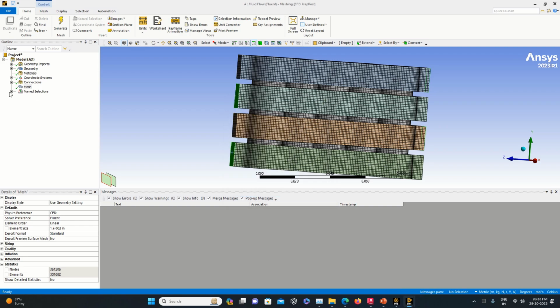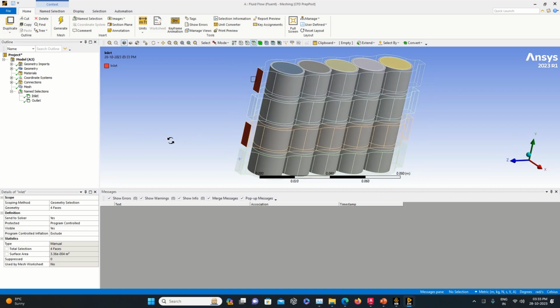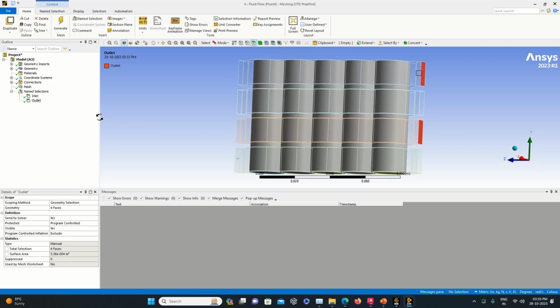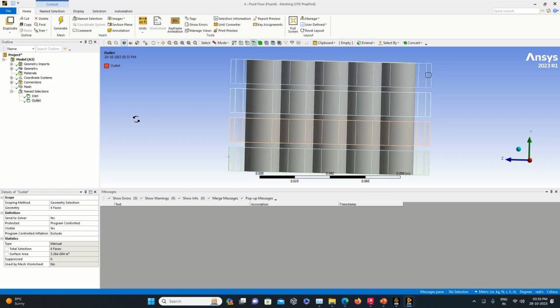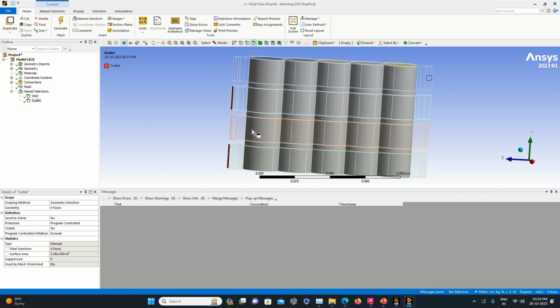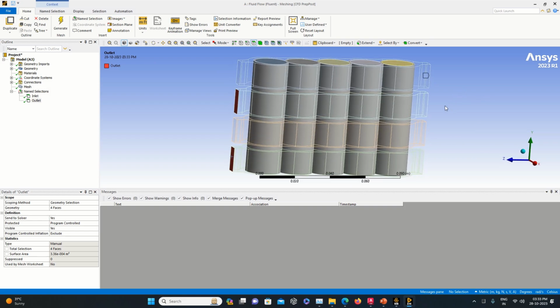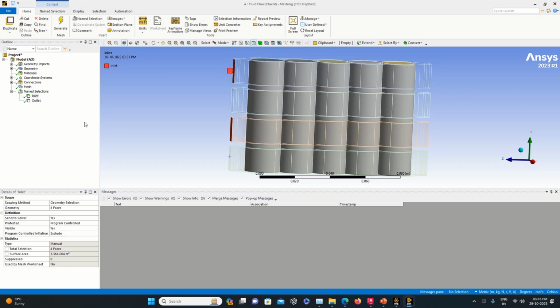Okay, so just check that there should not be conflicts in the boundary conditions. This is the inlet, and these are the outlets. So first one, this was the inlet, which we have specified, so it must be the outlet. This is the outlet, and from this fluid is coming in because this was inside the inlet, so they must be outlets. So accordingly we must check it.